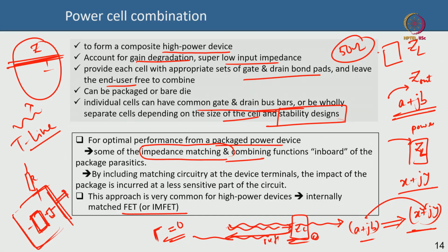That means outside the device, outside the package, looking in the package, you will see there is a 50 ohm impedance termination. So when you give this to a customer, could be a civilian, military customer, you can say that I have a package device which is internally matched 50 ohm. They will be very happy, they will take it, and then they know it is 50 ohm, they will have the system also at 50 ohm. They may have a load eventually at different complex impedance, but the idea is that 50 ohm is the universal impedance. So 50 ohm is very easy. You have 50 ohm, you can quickly match them. Okay. So 50 ohm is like the holy grail, it is like the universally accepted impedance that you want to match.